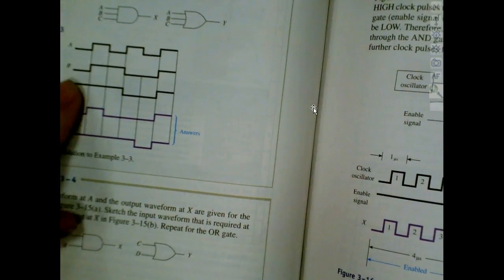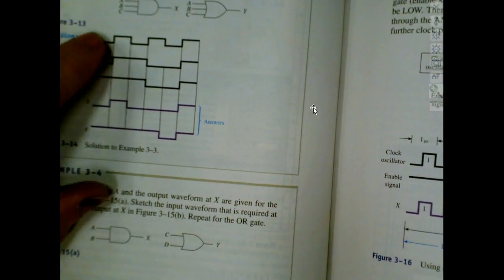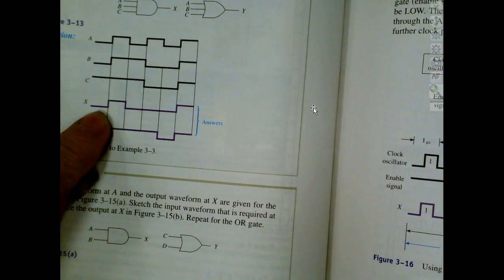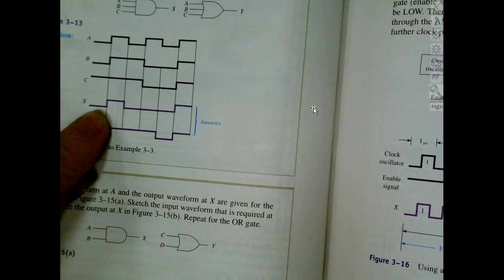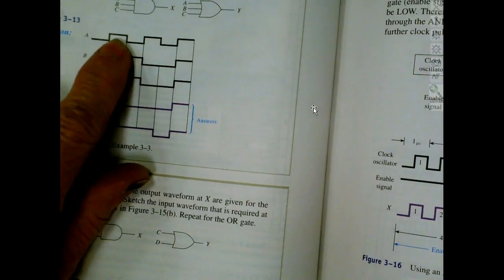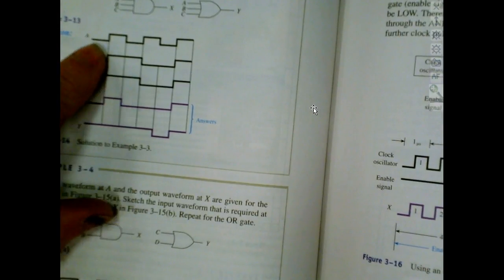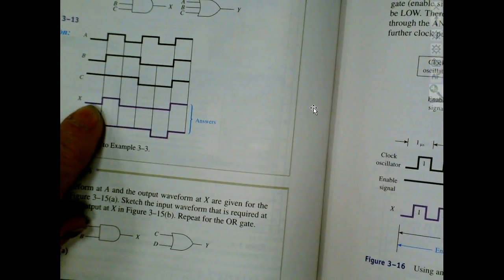But what we're trying to do is this is where the truth table makes sense. So what I could do in a truth table is I could look up this combination right here, and it would tell me the output would be low. But that would be one of 8 combinations, right? You understand? I could look at this combination right here, but if you understand all highs to get a high, then that is not all highs, so it automatically puts a low.